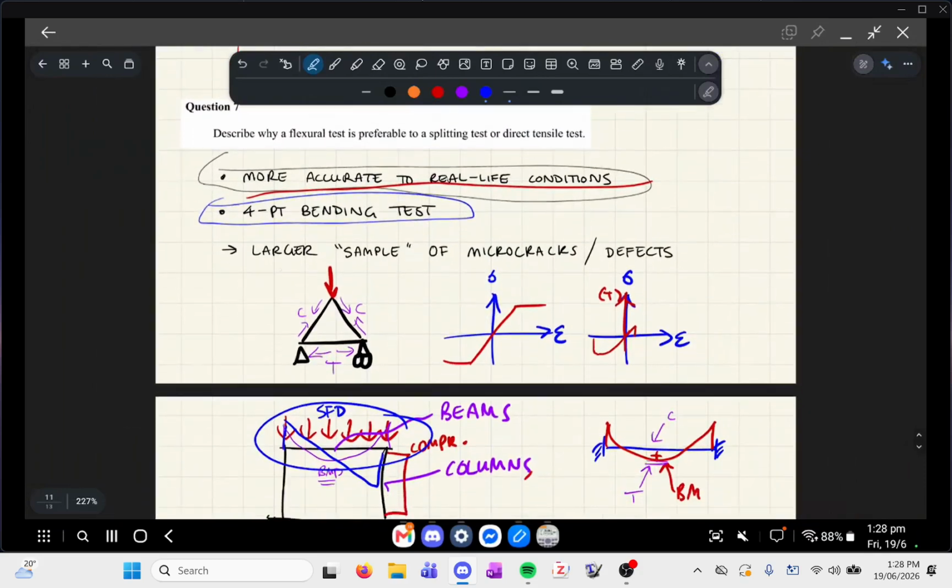Okay. And as I was mentioning before with my example about Leonardo da Vinci, the idea is that you've got this kind of size effect, right? When it comes to concrete and ceramic materials, if you have a larger sample of this material, like concrete, or like a rope that's being pulled, like an iron rope, you've got a larger sample, it's a longer rope, it's got a higher chance of micro cracks being present, which can induce fast fracture. All right.